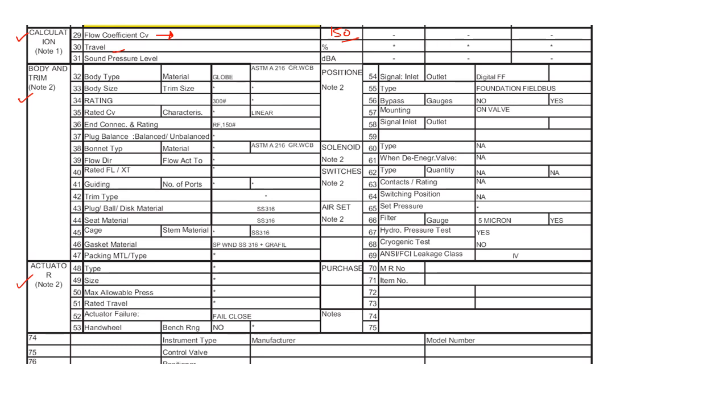Now this datasheet also can have multiple stages. For example, it can be a very initial stage, where the process datasheet is received by the instrumentation team, and they prepare the initial datasheet and then hand it over to EPC for further review and calculation.